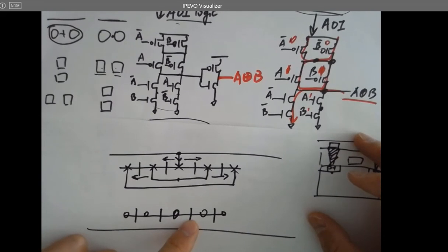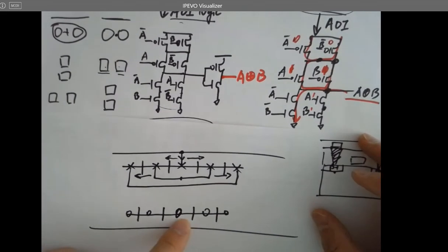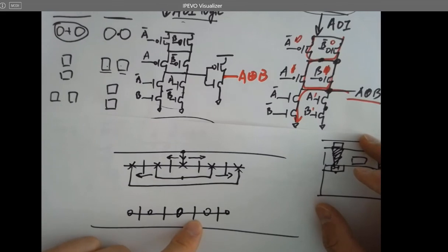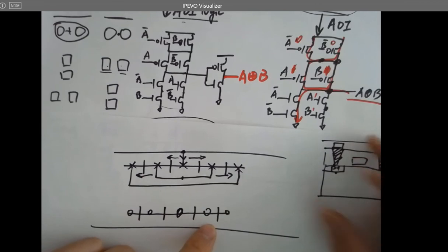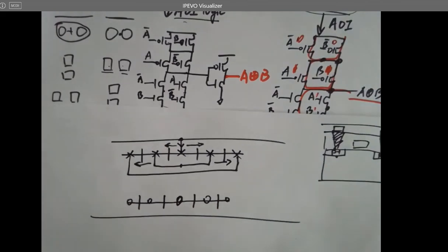But what's the indicator? When you are trying to count how many transistors you have in the circuit, you are looking at what? The gates. Whenever the current flows through a gate, it flows through a channel. One channel means there's one transistor, because that transistor is being controlled by the gate.